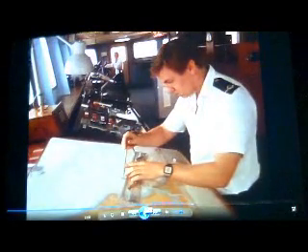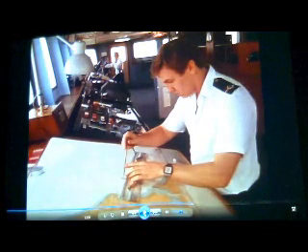We will stop the ship and see how it goes in the wind. What will matter is how deep the water is. We will do one with wind, one with current. Then one we will do with both wind and current, because then the ship's windage area will come into effect with the underwater area, because it is a balance of the two. At sea there will never be one condition where there is no current, and we'll put the ship without current, without wind in high waves, and see how the vessel drifts away.